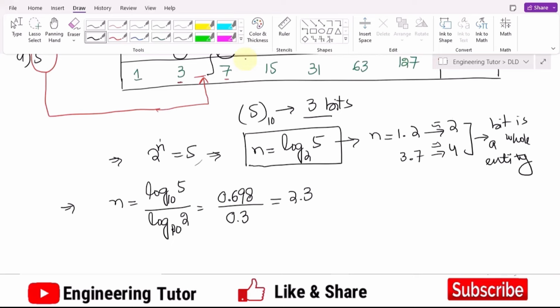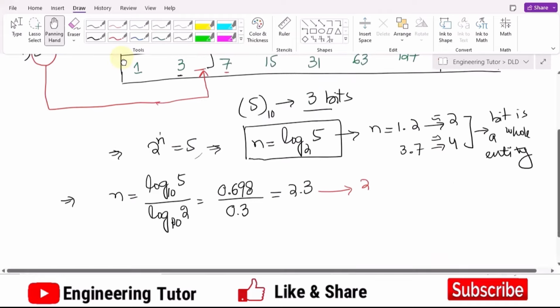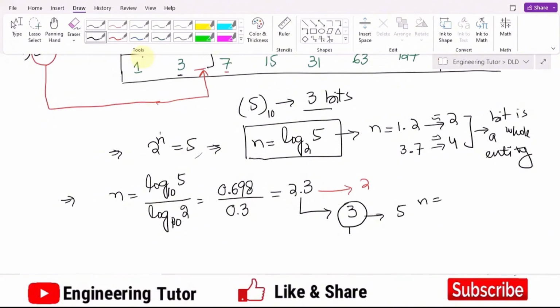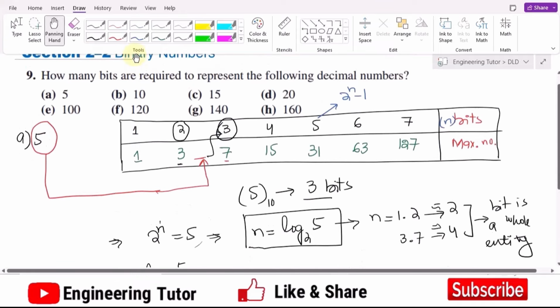But 2.3 cannot be the number of bits, since it is not a whole number. If I round it off to 2, I will get 2 bits, but the maximum decimal number I can get from 2 bits is basically 3, so it is not possible. Therefore, as I have told you, you always have to round it up to the higher number. So 2.3 is rounded off to 3. So 5 will be represented by 3 bits, and n will be equal to 3 for this decimal number 5. These are the two methods used for the calculation of the number of bits.